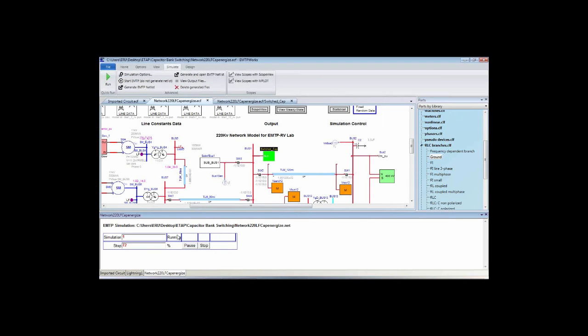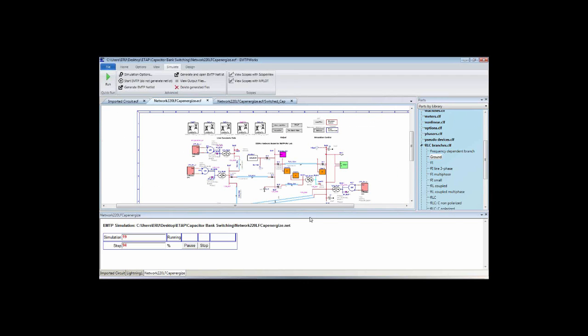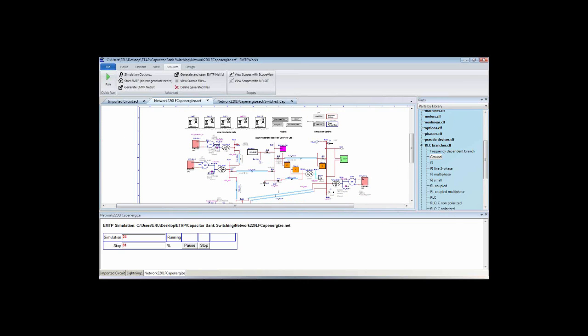It will be quite fast. It will last only a few seconds, even though we're running 50 simulations here. By the way, we can use the same statistical analysis for a lot of different parameters, for instance, transformer energization or cable energization. This allows you to quickly have a look at the worst of the voltage that can happen in your systems.